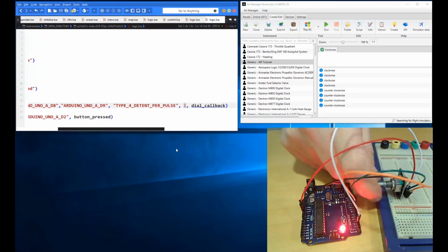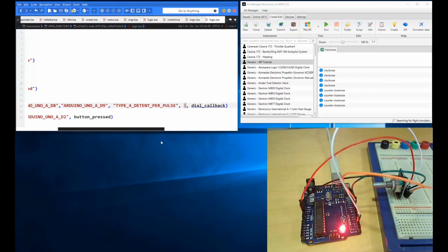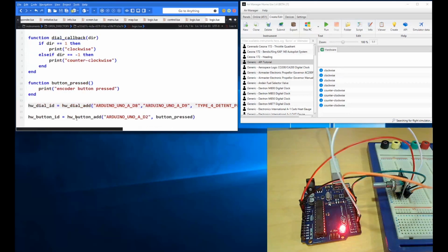You might be able to see what happens with that acceleration number as you change it. You'll see the effects, particularly if you use some prints in the console here. You'll get an idea of how many callbacks are getting called as you whiz that encoder around faster, and what effect this number has on how many callbacks you actually get. I'll leave you to experiment with that.